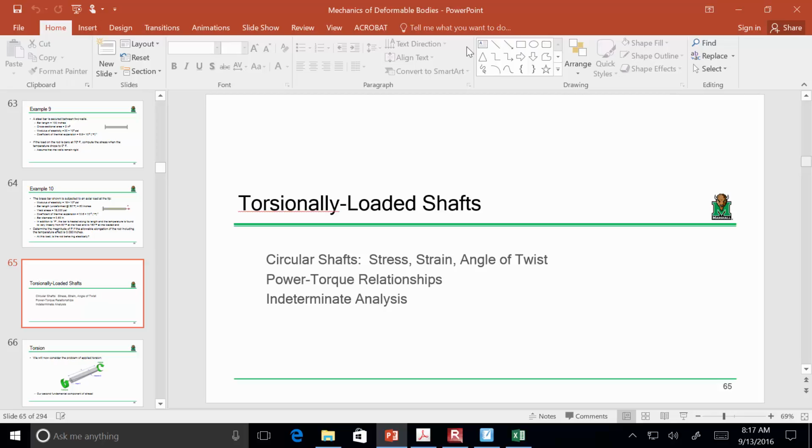Yes, sir? So let's say you find the deformation of that part that you assume to be 3, and then you want to pull it up. You do deformation equals PL over EA. Substitute in the value for deformation, and then solve for P. There you go. So let me sort of draw that on the screen to make sure everybody's clear on that.